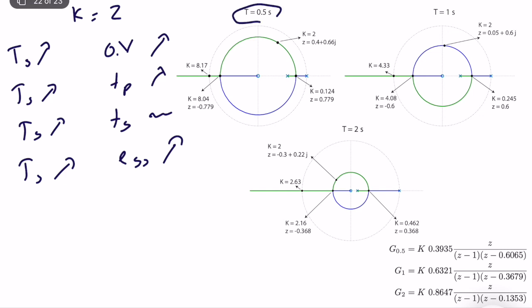Okay, and for this reason, in digital control systems, we really give a huge importance to the sampling time. It's being like constant as best as possible, and we would like to make it as small as possible. For example, in modern control system, in general, we want it to be 0.1 millisecond. Sometimes it can be higher depending on your plant, but in general, we really want it to be as small as possible to have a good performance in real time.